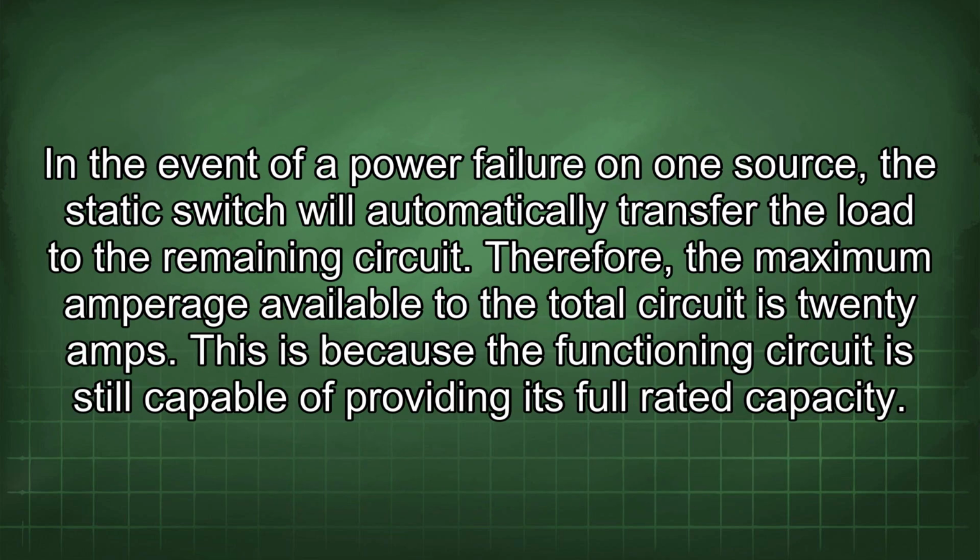In the event of a power failure on one source, the static switch will automatically transfer the load to the remaining circuit. Therefore, the maximum amperage available to the total circuit is 20 amps. This is because the functioning circuit is still capable of providing its full rated capacity.